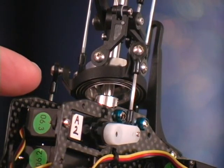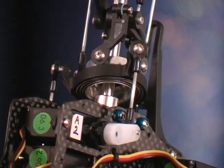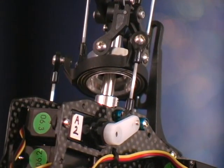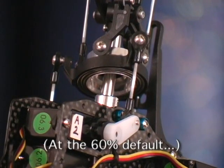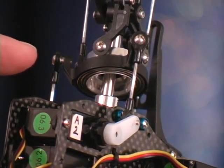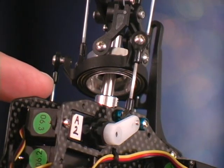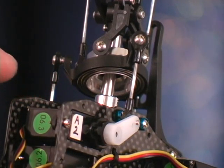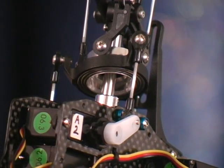Now, for maximum cyclic response, the swash plate would just almost touch that collar, and it looks pretty close right there. So I'm not going to change anything. I'm just going to leave it the way it is because, again, it looks good. If you had a different type of helicopter and the swash plate was farther away from the collar, you would simply increase the aileron and the elevator percentages equally in the CCPM or the swash mix menu.